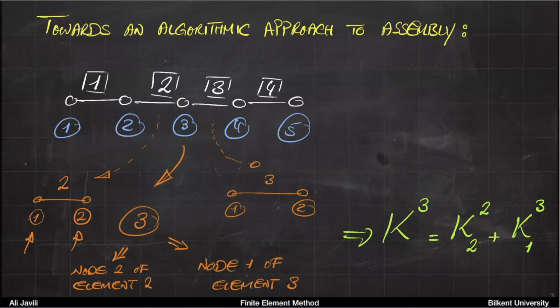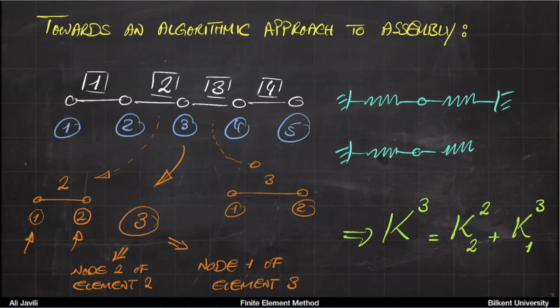Now, if for a quick moment you think of having two springs in series, you can see that this analogy is not exactly what we did there, because there we needed k1 k2 divided by k1 plus k2. So this is basically a system like this, just for simplicity. If it was two springs in series, it would be like that. Obviously this is not good, because if it is K1 and this is K2, the effective K was K1 K2 divided by K1 plus K2.